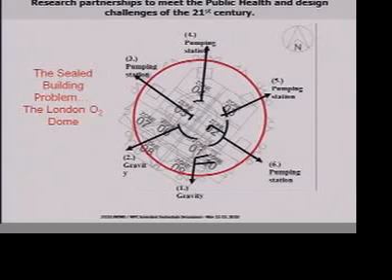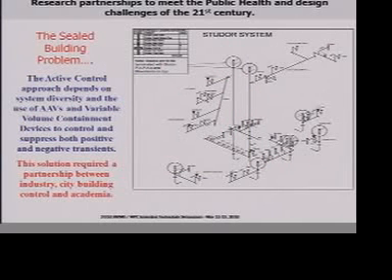So what we do is we connect all of the vent systems together so that we can vent quite happily, and then put in a mixture of positive pressure transient devices and negative pressure transient devices to allow us to design that system without penetrating the roof structure, which was not allowed by the city authorities.